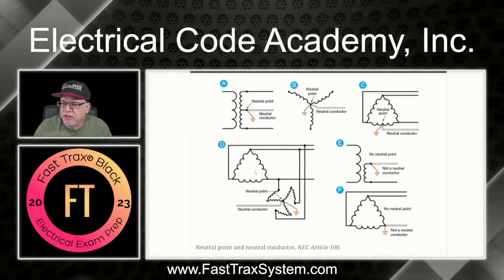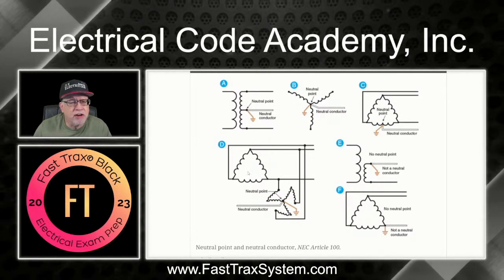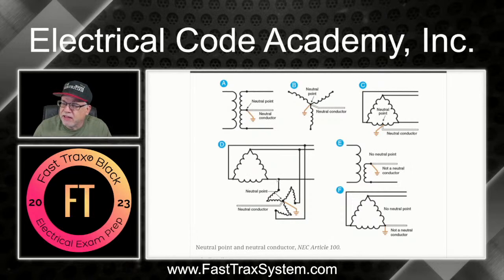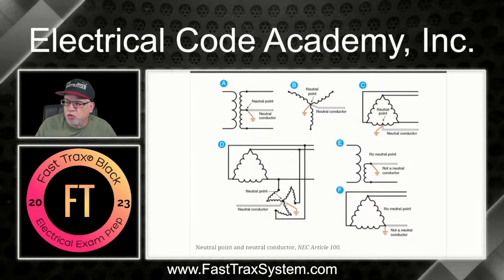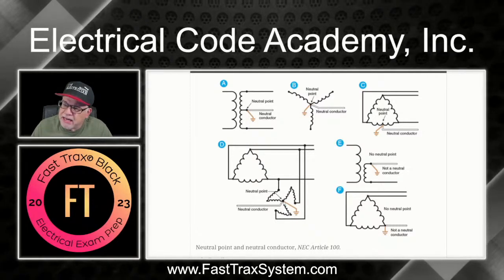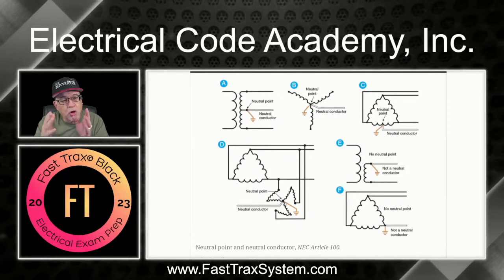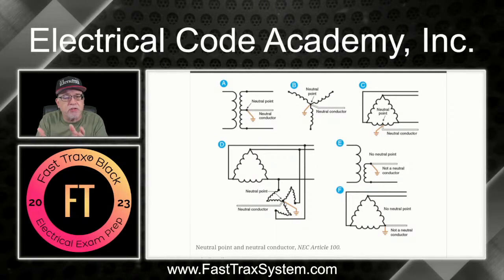Now, D is an example where we have a delta system, and this is obviously an ungrounded delta. Then you have connections that come down and hit a zigzag transformer, and in this one there's a neutral point here. This system is intentionally grounded, creating this neutral conductor. Notice this is derived from an ungrounded system. So this is how you can create it as well.